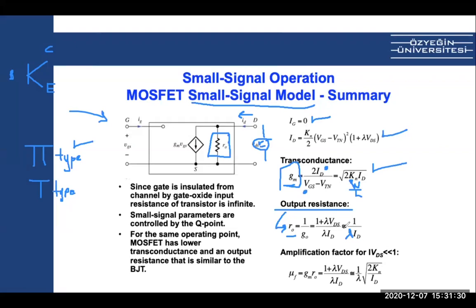And for a very basic MOSFET, let's calculate the amplification factors. So this is our input, VGS. I'm not considering the input resistance and stuff, just this MOSFET. So this is the input, and this is the output. So input times GM is GM-VGS.